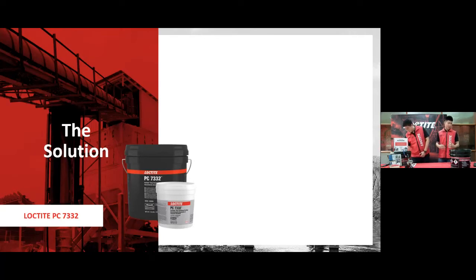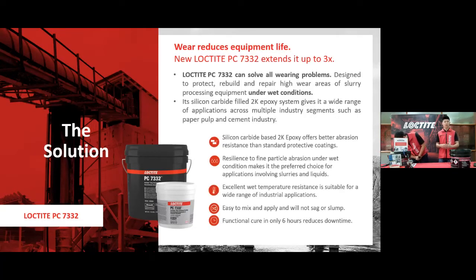Why do I say that this product is the answer for wet abrasion or slurry abrasion? The reason is that inside this product, we have silicon carbide filling materials inside the epoxy. These fillings provide outstanding resistance towards wet abrasion or slurry operations in your plants. As usual, the benefits of using this product are like what Eng said: easy, sag resistant, able to apply on curvy surfaces, and the curing time is 6 hours. At the same time, I have one very interesting video to show the performance of this LOCTITE PC 7332 on wet abrasion using ASTM testing.